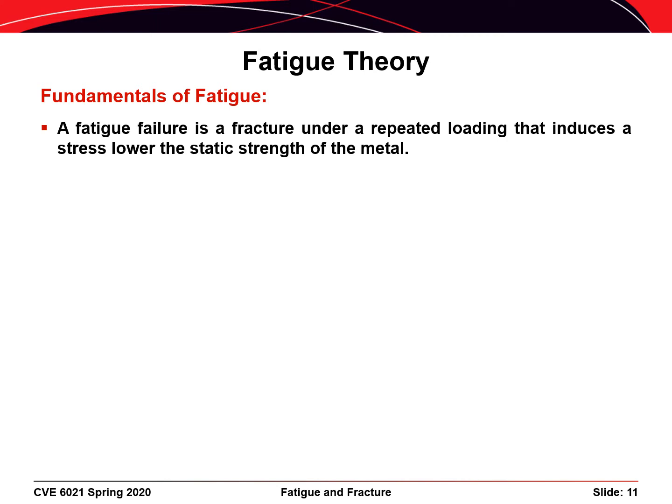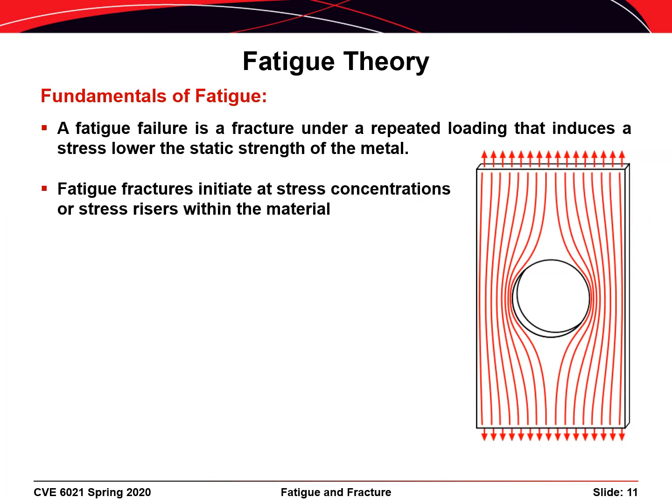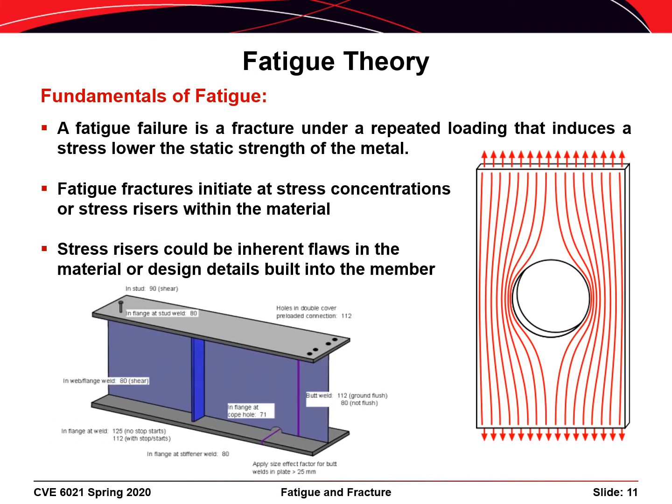All right, to summarize where we are so far, a fatigue failure is a fracture under a repeated loading that induces stresses that are lower than the static strength of the metal, the yield strength or the buckling strength or the tensile strength. Fatigue fractures typically initiate at stress concentrations or stress risers within the members, like the hole in the plate on the right. But in theory, they can initiate at any discontinuity, including very, very small flaws that are inherent in the material itself.